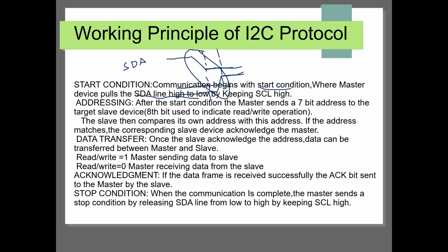So if we keep changing the SDA line continuously while maintaining the clock high, there is no use. Communication is not happening properly, because every time you change it, which data do I want to communicate? That should not happen. That is an I2C protocol violation. When you can change the data, SCL should be in low condition. You can change the data then. The SDA line you can change anytime while SCL is low. That is possible and is not a violation of the I2C protocol.